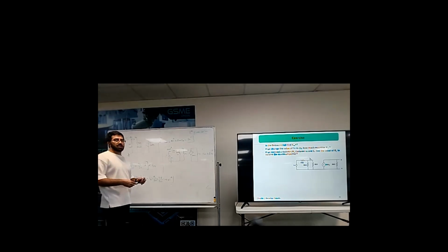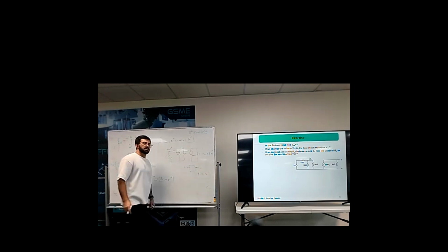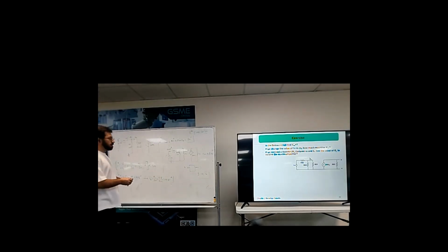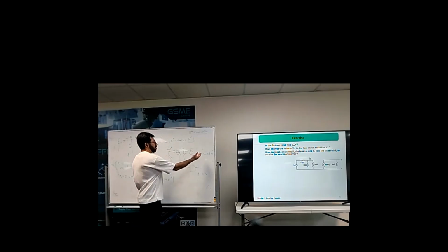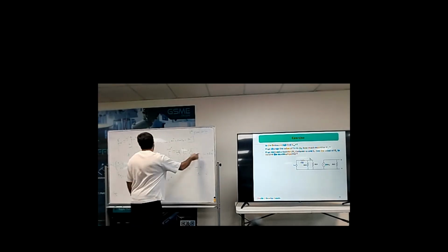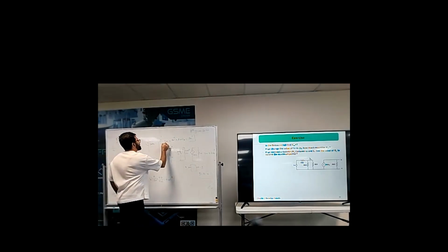Exactly. That's linearity. Yeah, we call it linearity. If you have a system, we will see it in the next course. If Y is alpha X, this is a linear relationship between Y and X, input and output. If I consider VRB as the output and this voltage source as the input, I can find VRB if I write this as V in and VRB as the V out.